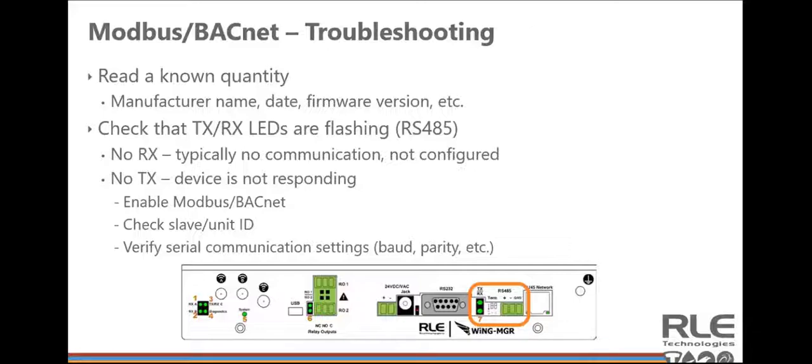Check that it has the unit ID you expect. You also check to make sure you don't have the wrong wire polarity. And of course, you'll want to verify your serial settings like the baud and parity.